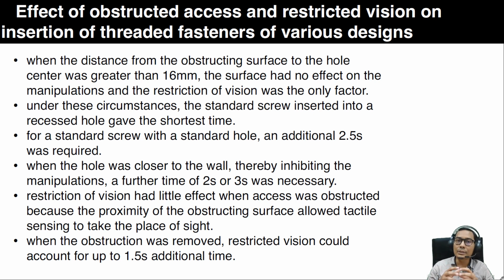Under these circumstances, the standard screw inserted into a recessed hole will give the shortest time. For a standard screw with a standard hole, an additional 2.5 seconds was required, and when the hole was closer to the wall, thereby inhibiting the manipulations, a further time of 2 to 3 seconds was necessary.